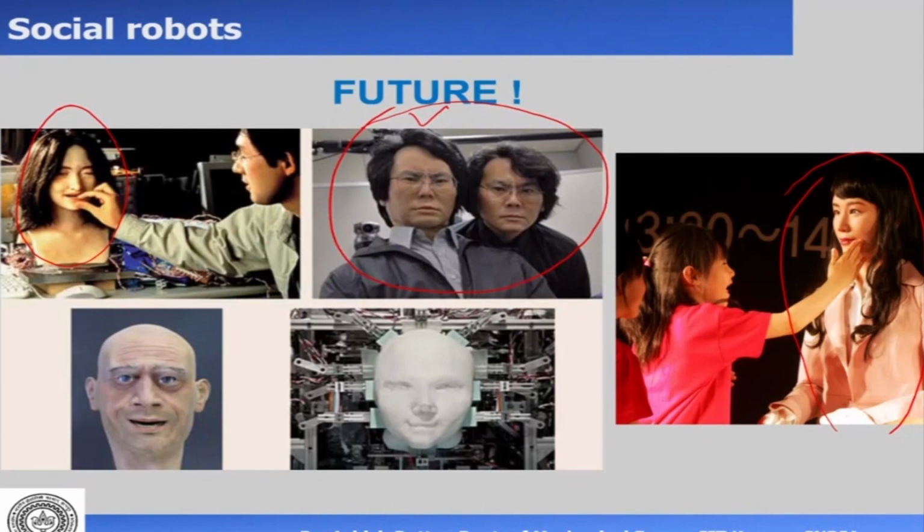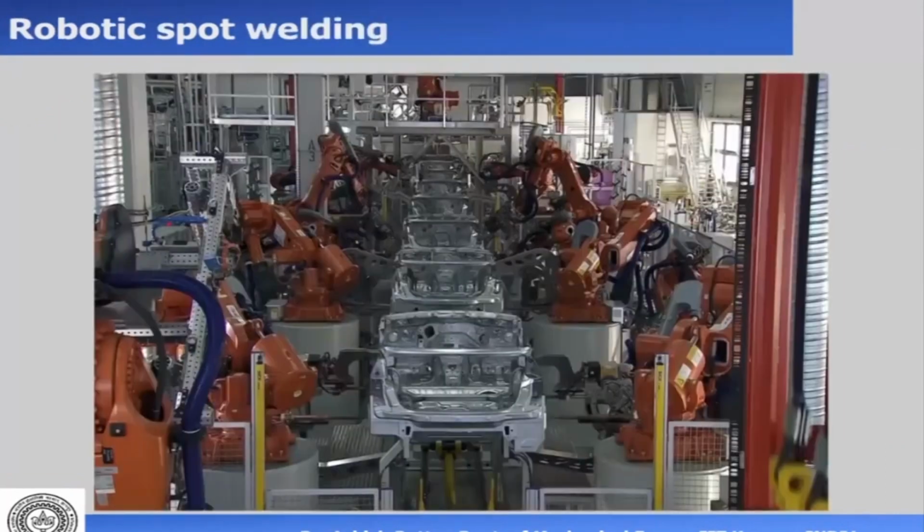Now, in terms of industrial robots, our industrial manipulators were arms of this nature, okay, for doing tasks. Now, these arms are kept inside cages or boundaries. So, for example, if you see here, there is a boundary here, and the robot is inside the boundary, and there are no human beings here. The human being has to be outside the boundary. Now, that is basically for safety, because these robots are industrial robots. They're very, very strong. If they were to hit a human, okay, then the human can be very, very seriously injured. So as per industrial laws today, the robot and the human do not come in the same workspace.